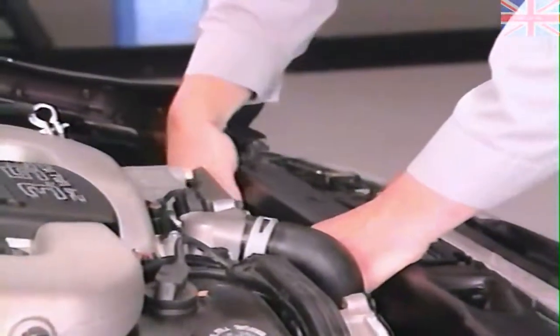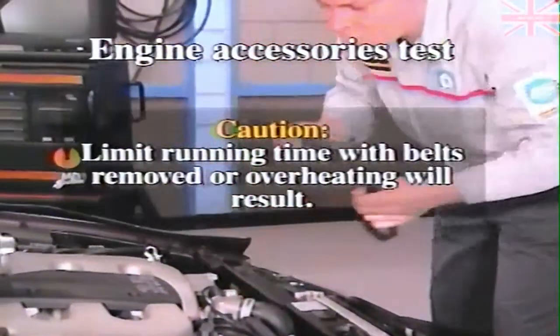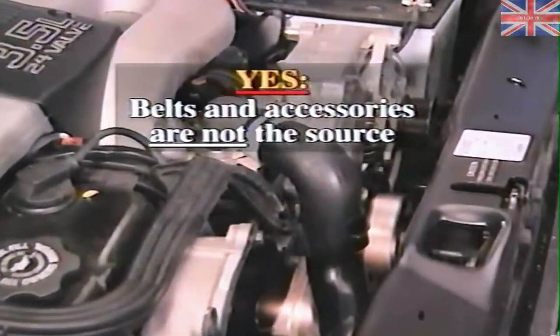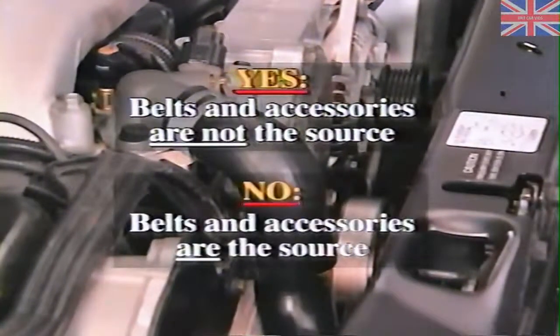Remove the accessory drive belts and increase engine speed to the RPM at which the noise or vibration occurs. If the problem persists, you can eliminate the belts and accessories from consideration. If the problem goes away, the trouble source is either a belt or an accessory problem.